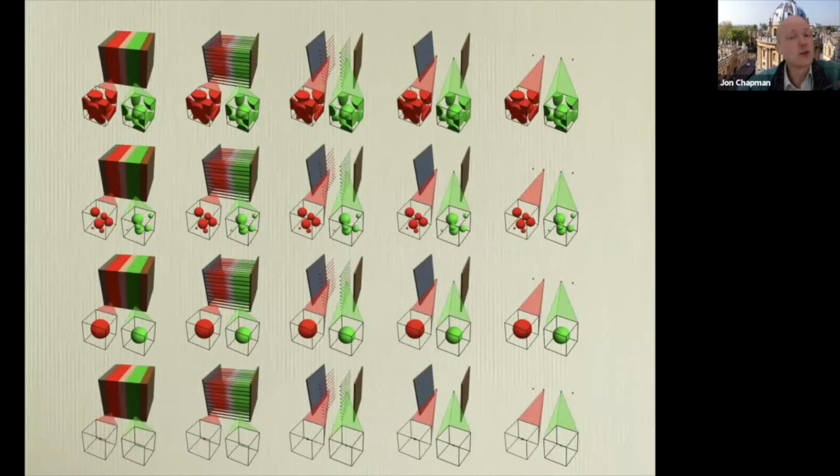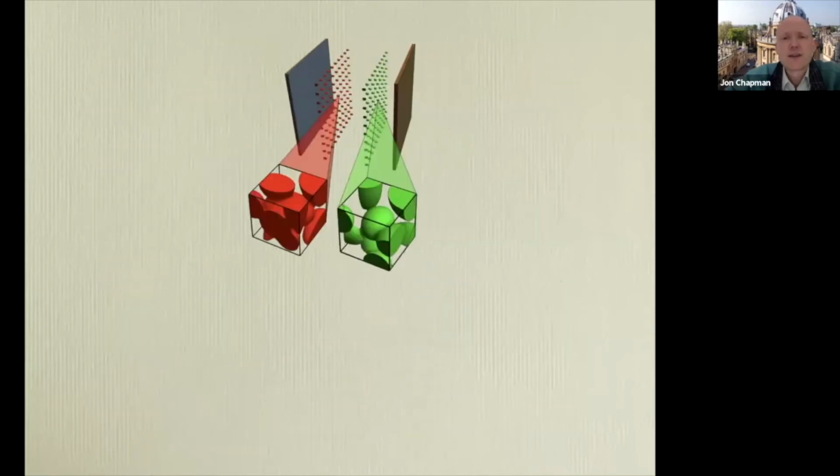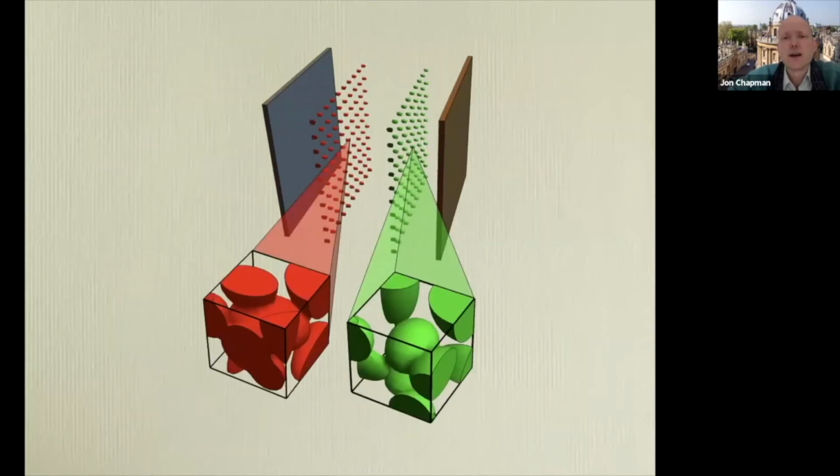And then if you do it the other way and you say, I'm going to take the limit in which the electrolyte is very conductive, or the timescale for diffusion is small by comparison to discharge time, before I take the high current limit, then instead of getting a sequence of DFN models all coupled by the boundary conditions, you would get a sequence of single particle models, or a grid of single particle models, all coupled through the two-dimensional current collectors at the end.